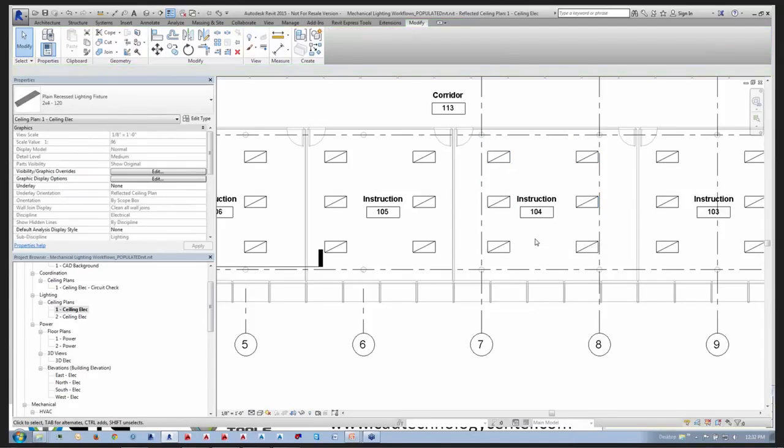They're going to look the same either way, and so you might easily lay out an entire floor of light fixtures or an entire portion of that floor on that specific reference plane, and you wouldn't even know until you happen to look at it in section view, and at that point you can't just grab that reference plane and rotate it.